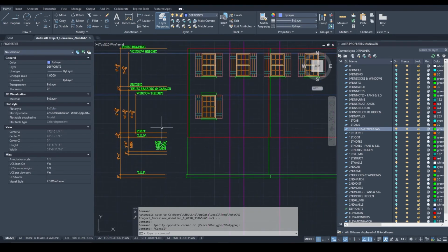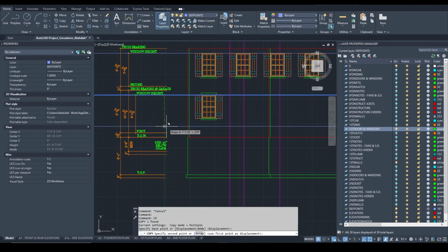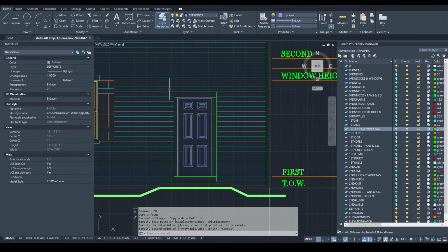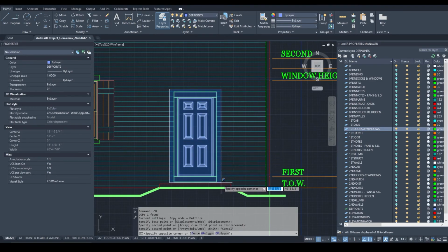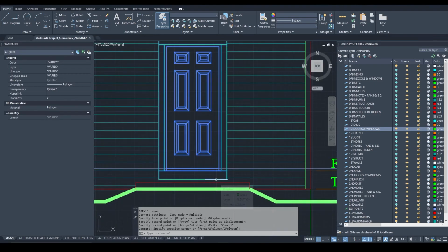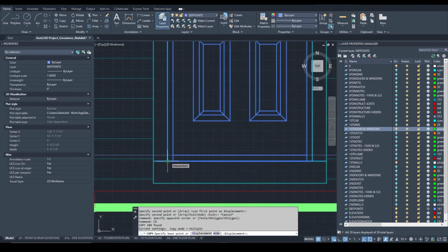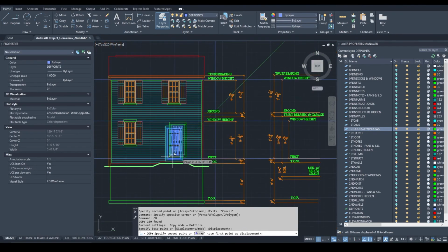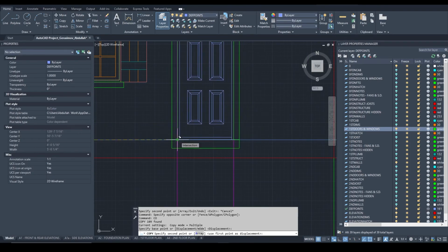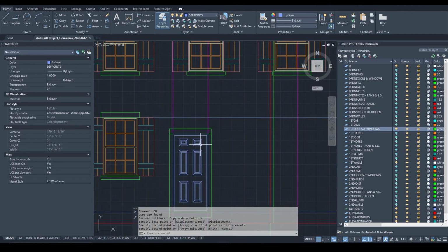The next thing on our list is to create a door. We're going to copy the reference line from the window height to the first dimension. And once we do this, we're actually going to copy the entire thing on our left and align it. Since it's already aligned to the first level, we're going to copy the entire assembly from the corner of our bottom trim or left side trim and align it to the same location over here. As you can see, this is our door and it's exactly the same size.